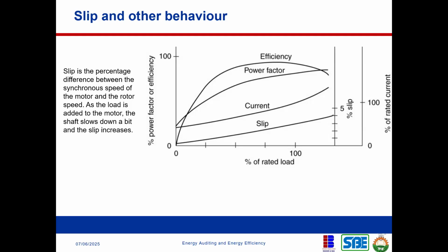So that's the rotation of the flux, right? Which is then attached to a rotor, right? Now, sometimes the speed of the flux can vary from that of the rotor. The rotor can also be the shaft that you're seeing, the shaft where you can now attach maybe your belt and every other thing, right? So the difference between that magnetic flux of the motor and the rotor is what we know as slip.